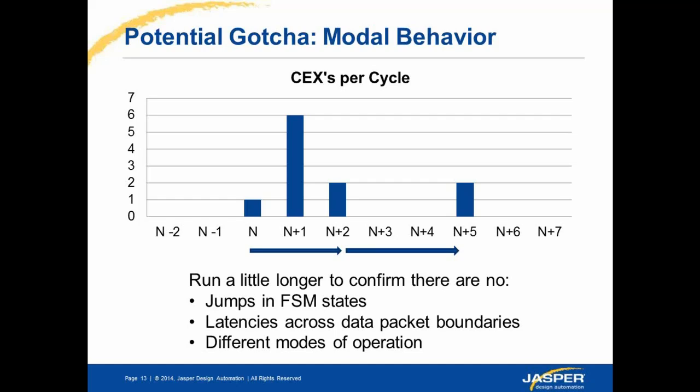So these are in the proof core or the fan-in cone of the property, and you need to run it to a depth of at least 32 or 34, whichever is the suggested depth by the tool, to get more confidence in your bounded proof. If you run it to the depth of 32 or 34, does it mean that there are no more counterexamples? No. It means that the tool has gone through or visited all states till a depth of 34, and it has not found any counterexamples.